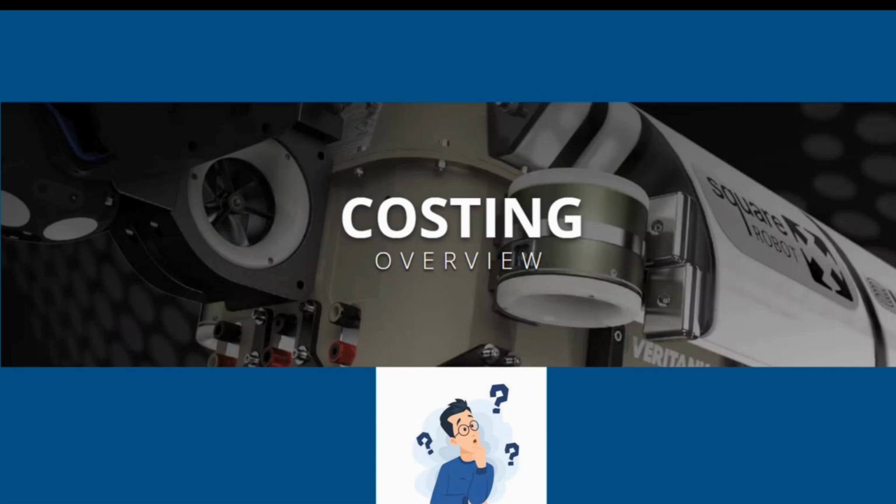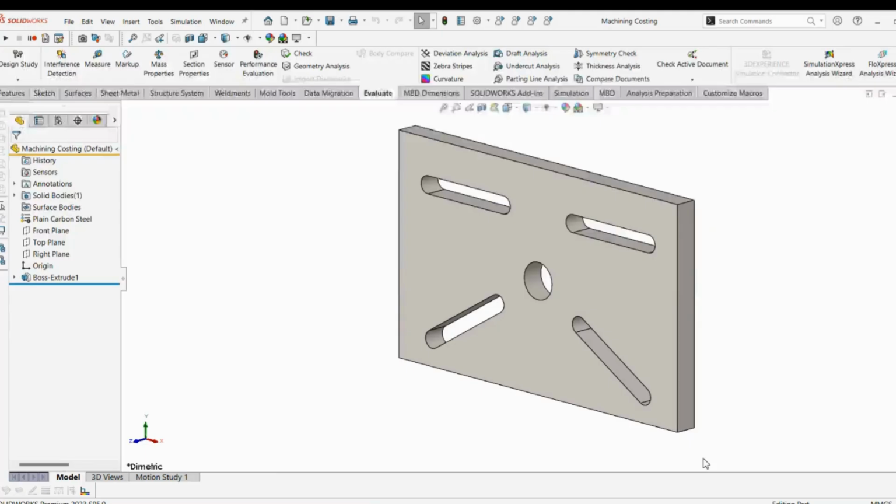So let's start with our costing feature. First we will open SolidWorks, and in SolidWorks, in a part document, go to the Evaluate tab in the CommandManager. Here the Costing feature will be there.